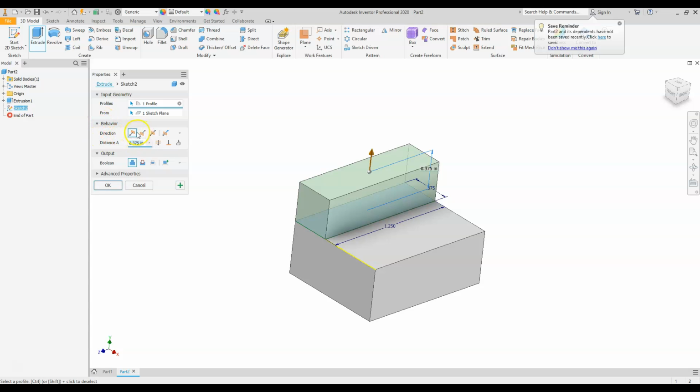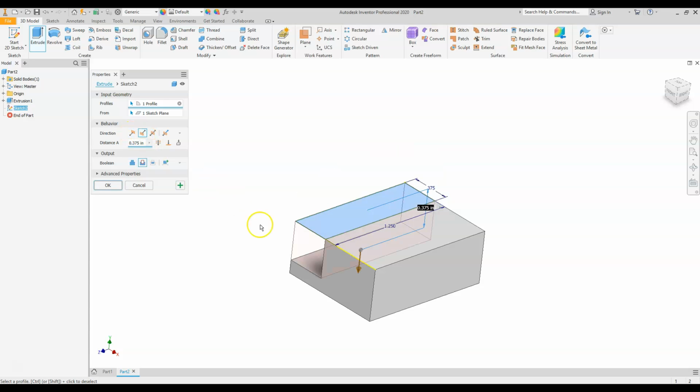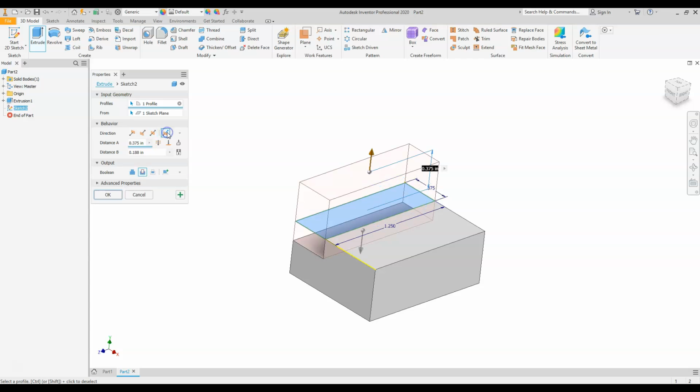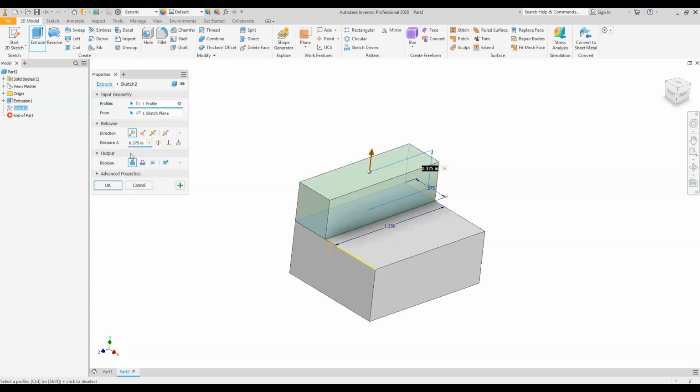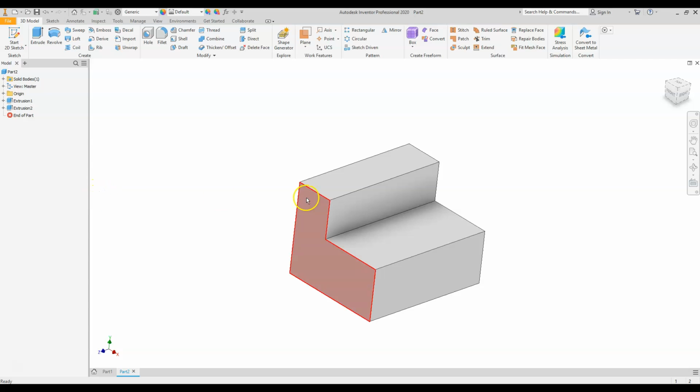While we're here, look at the directions. The directions are laid out. That's your default. This would reverse the direction, so you can see what happens when that reverses. It automatically switches into the cut mode because it knows that there's material already there. It could split the difference, and you can do an offset dimension. So we just want it to be default. We want to be joining onto the existing piece that we already have, so we're going to hit OK.